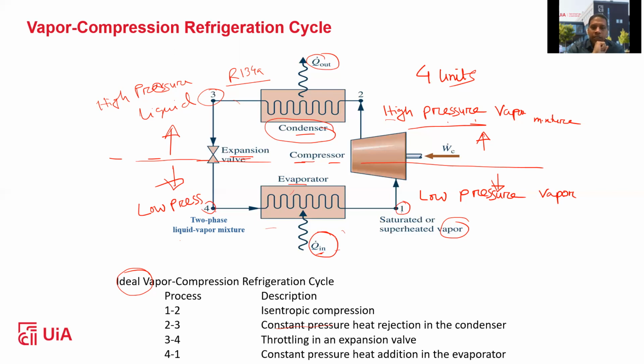And now in this case we talked about the ideal case. So we are saying, okay, there is no change of entropy and there are no losses in the pipe, because you know this is the pipe. If you don't have an additional insulator on those pipes, as I show you in here, you can actually lose a lot of heat to the environment.